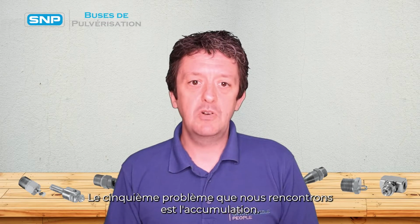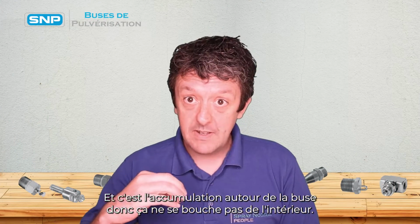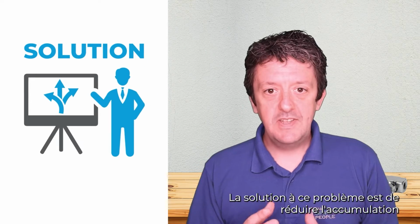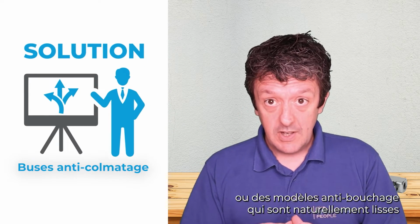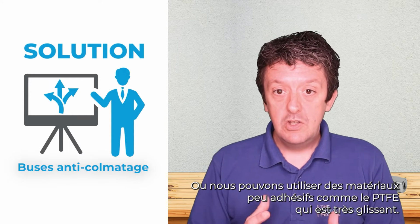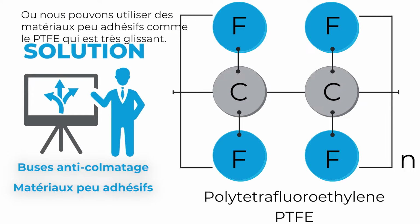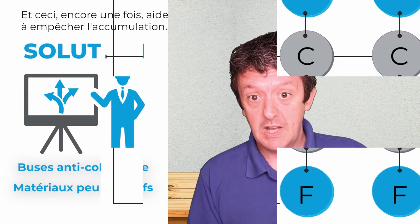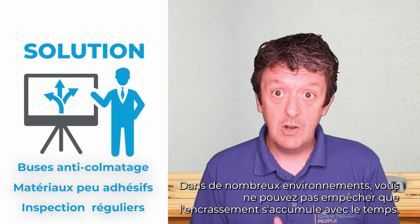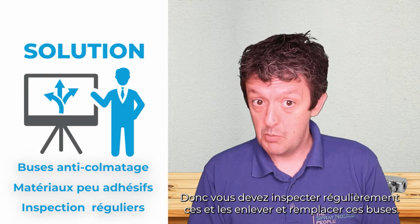The fifth problem we come across is caking, and this is build up around the nozzle. So it's not clogging from within the liquid, it's building up of material that gets onto the nozzle from outside. And the solution to this is anti-bearding or anti-clogging designs that are naturally smooth and don't have places for that matter to build up on. Or we can use low adhesive materials like PTFE that are very slippery, and this again helps prevent that from building up. But again, also regular inspection is key to this. In many environments, you can't help but caking to build up over time, and so you need to regularly inspect those and remove it and replace those nozzles.